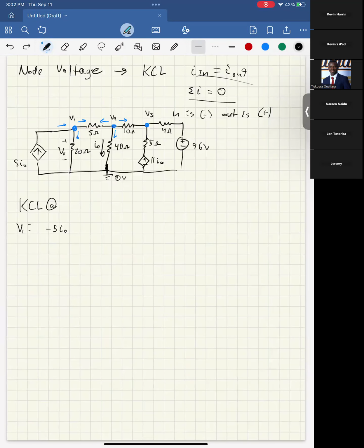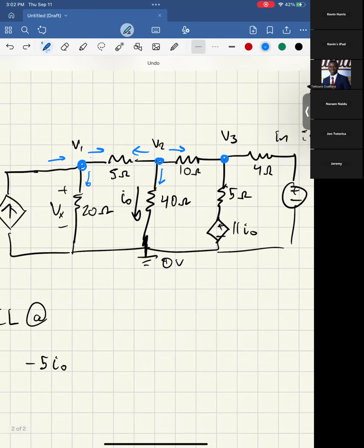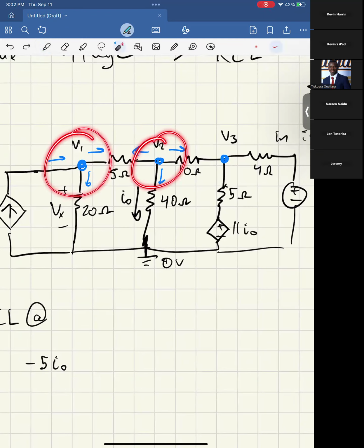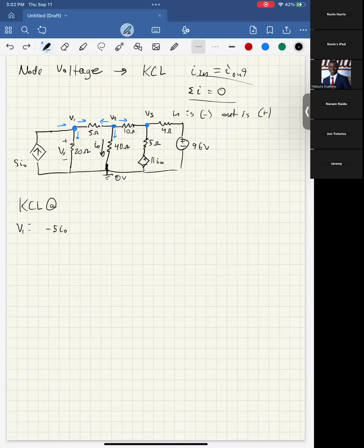But in that case, you already have two currents going in two directions, like where the 5 ohm is. That's fine though, because this will be in two separate equations, and this one will end up being positive and this one will end up being negative. If this one's negative, then it's telling you that it's actually going that way, and the math turns out fine. In your drawing, it looks a bit weird, but I can assure you, if you do it like this, the math will be so much easier, and you will thank yourself for it. I'll show you what I mean in a sec though.